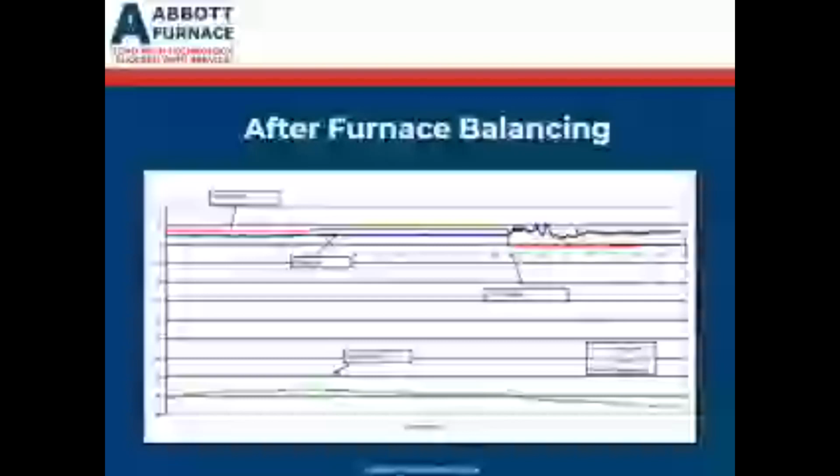Back in the cooling sections where the product is getting colder, we don't need hydrogen back there to react because our parts are cold enough to not oxidize. So we balance to maximize the flow and to push out the front of the furnace to remove all those vapors and prevent the buildup. You can see the oxygen in the heated zones, we maintained a very low oxygen.